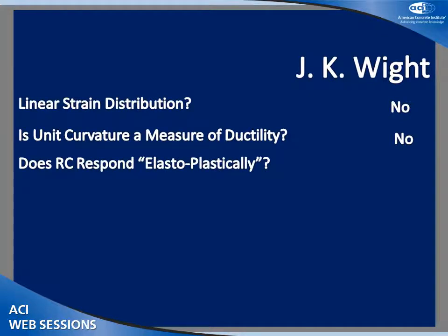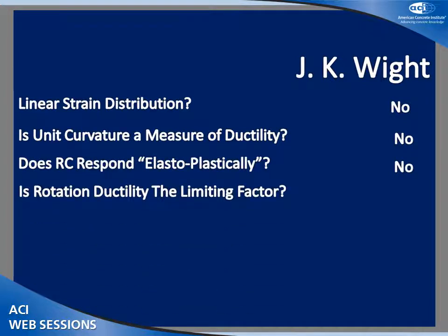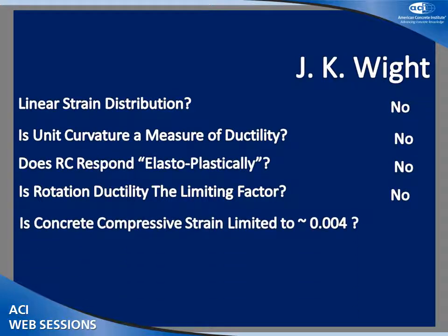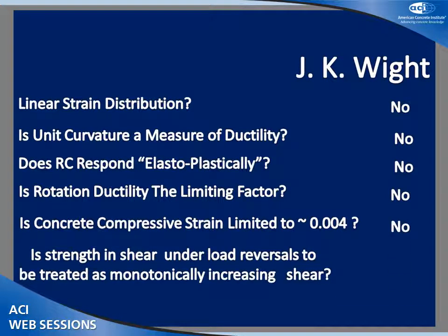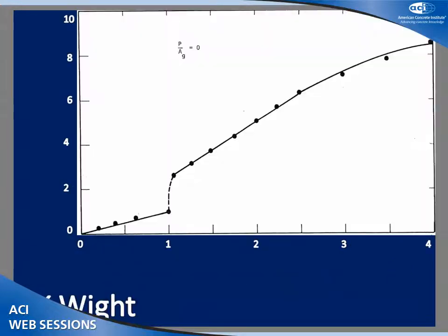Does reinforced concrete respond elastoplastically? Well, you know the answer to that. Is rotation ductility the limiting factor? Hell no, he says. Is concrete compressive strain limited to 0.04? No, he's talking about 1% that he has measured. And shear, again, no. But look, in one case, he actually responded positively.